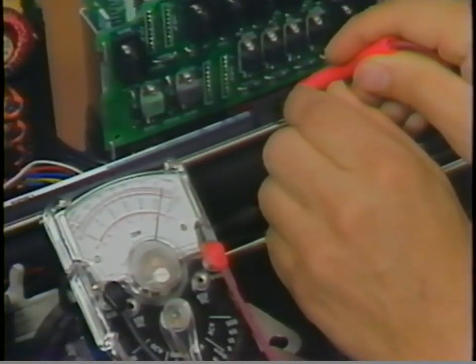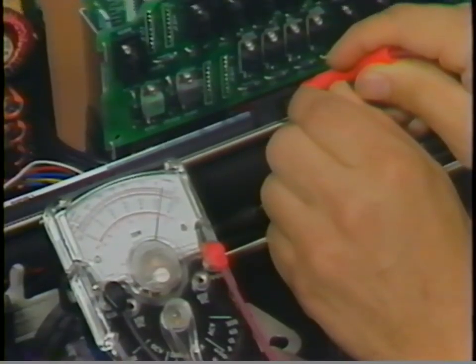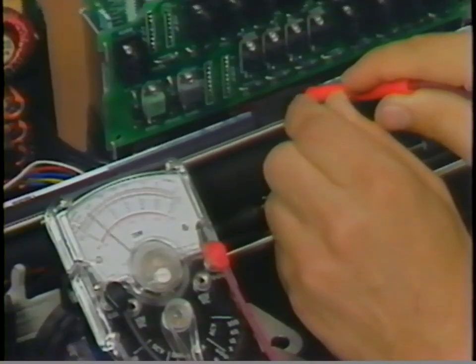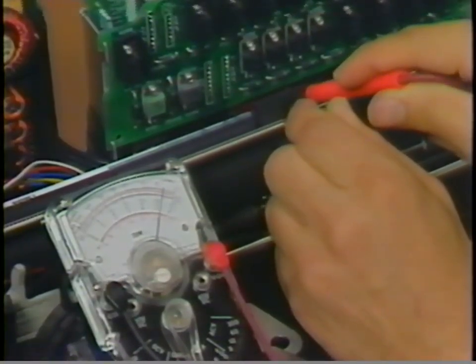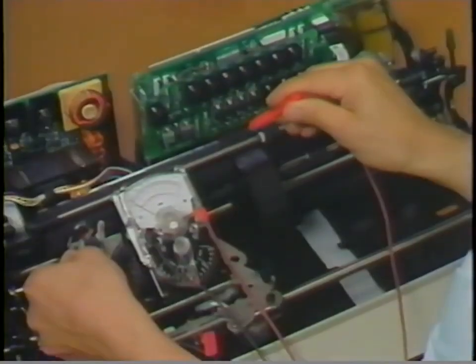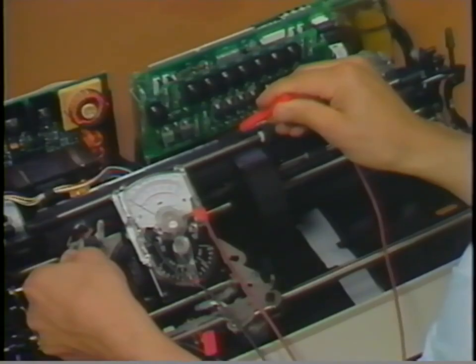Check the resistance from pin 4 to pin 7, SC to SC+, and from pin 8 to pin 5, SB to SB+. Next, check to be sure that there is no continuity between the motor housing and the selection motor pins on the carrier cable.